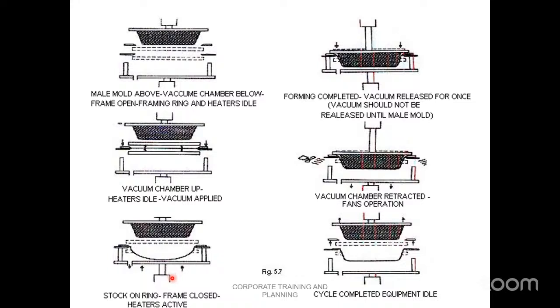Now the vacuum system will come up now. That time again you have to apply some vacuum here. Slowly you have to apply the vacuum, not 100%. Okay. Now see, here they have applied 100% vacuum, and the sheet is taking the form of this male mold here.